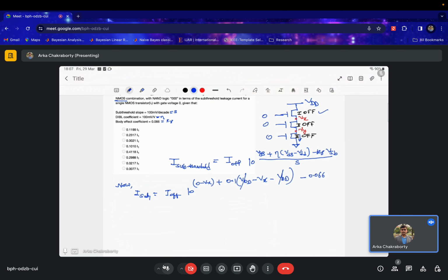So to remove the body effect completely, we ground the body of NMOS and apply VDD to the body of PMOS. But one more thing: the threshold voltage of transistors can also be shifted using the body terminal. Sometimes this is used to tweak the threshold voltage of devices, and further to design skewed inverters and similar circuits.